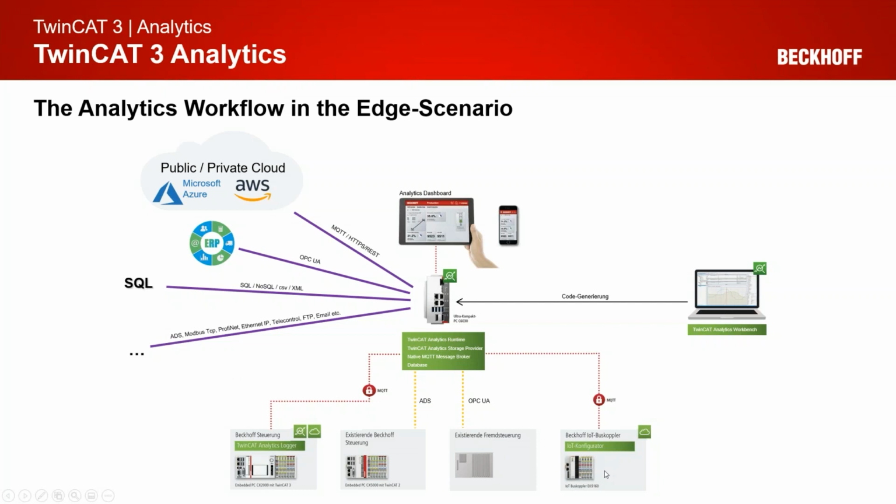Also, in the same way, the EK9160. And then we can use the data agent, or you can do it natively, the communication by ADS or OPC UA to other devices. So you can do it also in a programmable way. And then we have everything in this device and can calculate the results with the analytics runtime with all the algorithms that we have configured in the analytics Workbench, where we have done the code generation.